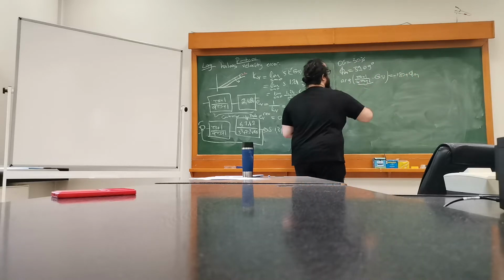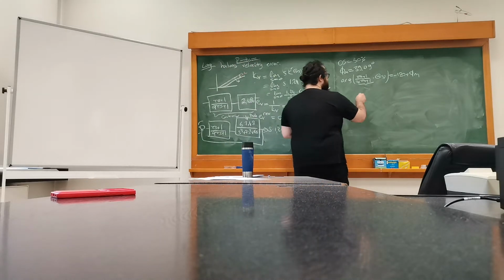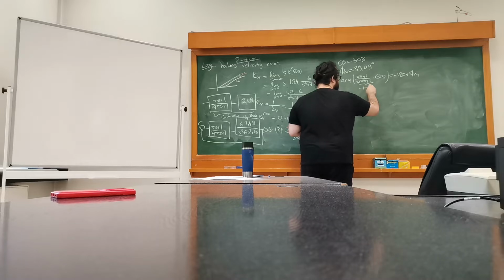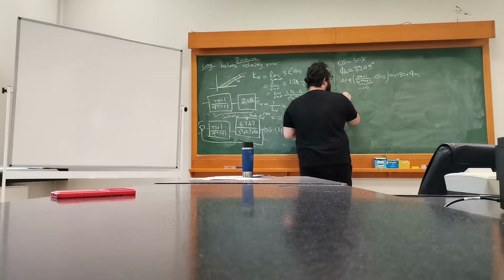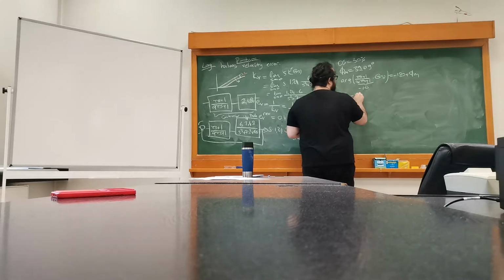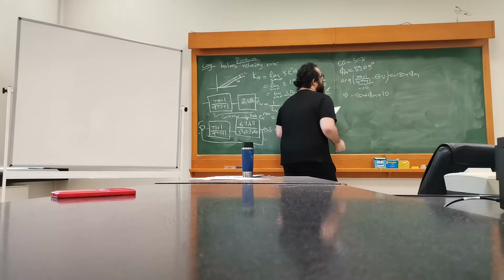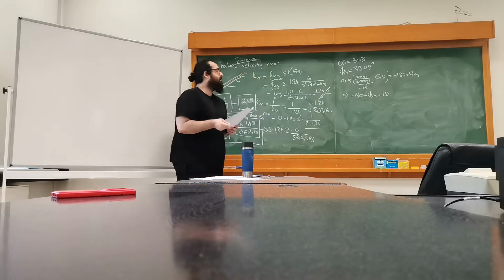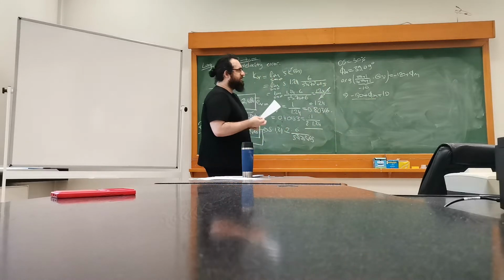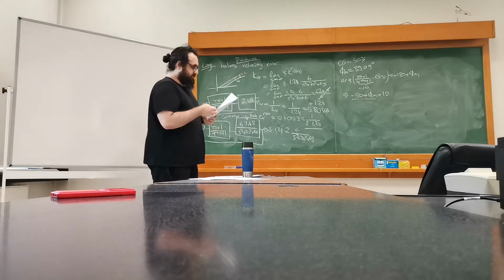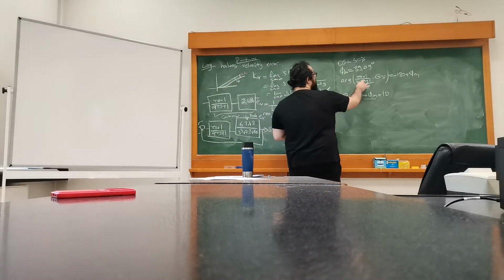Even though we have designed a lag controller. So therefore, if this is, for example, minus 10, then you'll see that it becomes plus 10. So if we are searching for the phase graph, we'll search for plus 10. Because if this will contribute negative 10, since it's a lag controller, we'll get the same phase angle there. So we are trying to be safe a little bit, or to compensate the value that will be added from the lag controller. But the basic assumption here is that it should be less than or equal to 10 degrees.